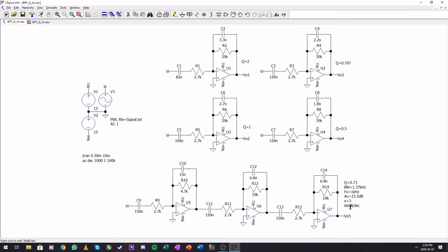So this is a third order bandpass, not ideal one, but third order. We achieve our gain and we have a very small bandwidth and a better Q. So if you really need to get rid of noise, you can just cascade some of these filters. But remember, start with a lower gain at the first amplifier and increase the gain as you go.